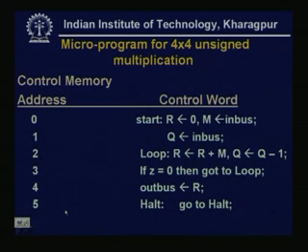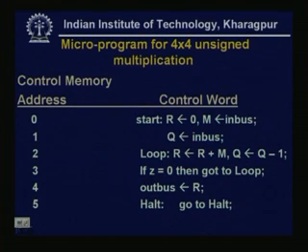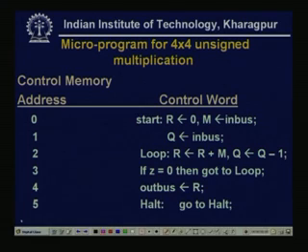Now, consider the design of a microprogrammed control unit, and the example we have taken is the same example as that of the hardware control unit. We have considered a 4 by 4 unsigned multiplication. The technique is repetitive addition.